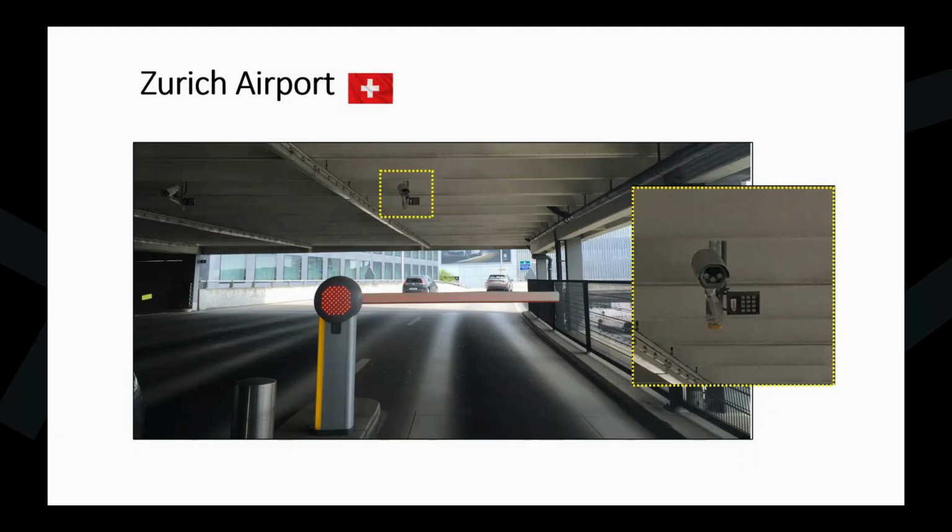In this particular environment, though, of course, it can be used throughout the day because obviously the airport's open until very late at night, especially this particular airport being quite a big one, and different weather conditions. Obviously, for this particular camera inside, not so much of an issue, but for the ones outside, you get all sorts of different weather from snow, rain, sunshine. And with regards to this particular camera, obviously low light with it being inside without very much general area lighting. In essence, the infrared in this case is absolutely a prerequisite in order to capture those plates reliably and allow for that system to work effectively.